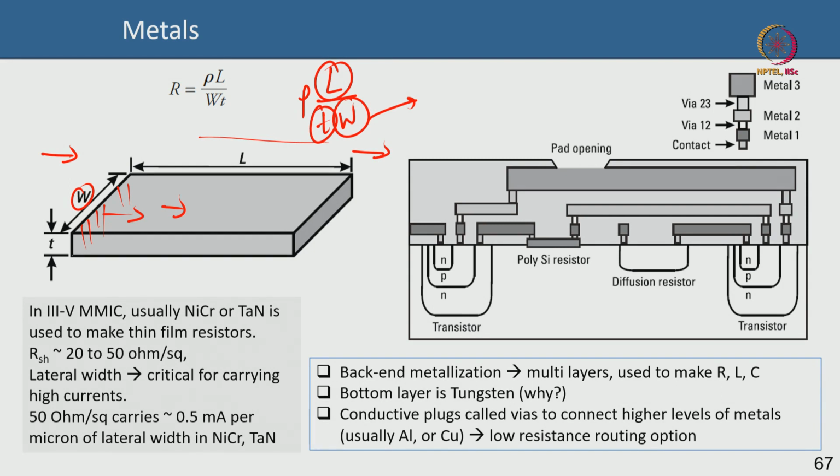For instance, in this picture here, I'm showing you a silicon CMOS based process, where the uniqueness in CMOS is that you have a lot of these dielectric interconnects, tungsten plugs. You can see the via holes. These are all back end of the line. The thickness of the layer becomes more and more as you go up, because you tend to carry more and more current as you go up. You are collecting current from different lines and feeding them up, so the metal becomes thicker, bigger on the top.